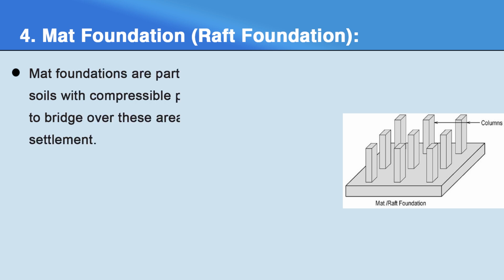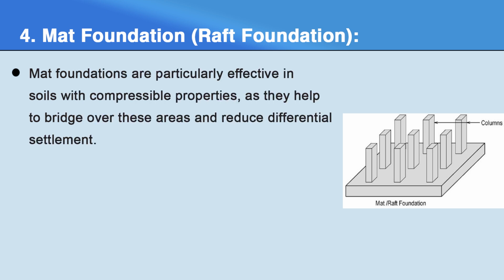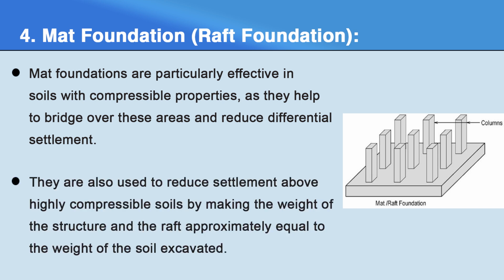Mat foundations are particularly effective in soils with compressible properties as they help to bridge over these areas and reduce differential settlement. They are also used to reduce settlement above highly compressible soils by making the weight of the structure and the raft approximately equal to the weight of the soil excavated.